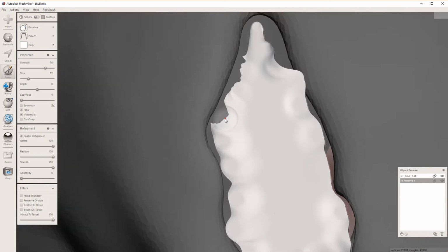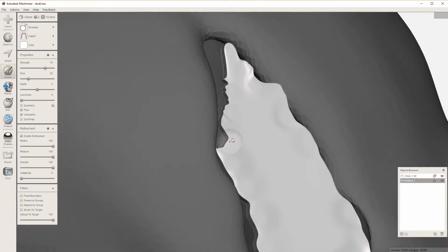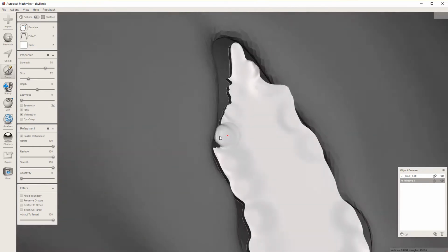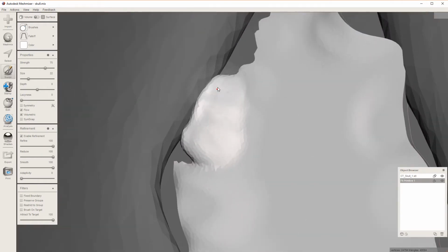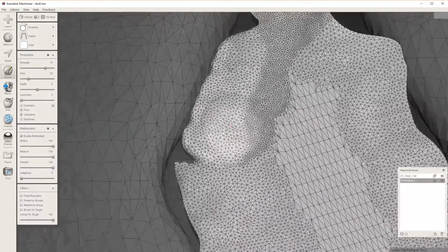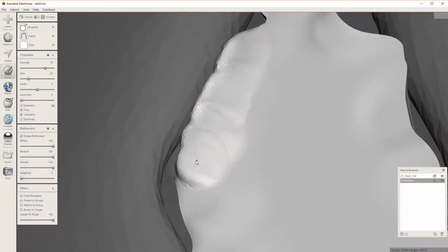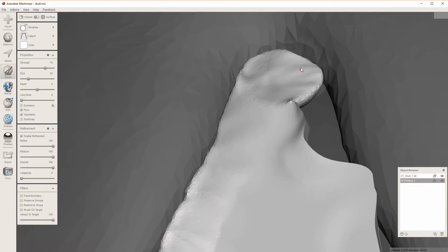Now what happens is, I'm recentering my view with the C key, by the way. Let's go right here. Now, when I click on this, it's going to get sucked to the closest target, the closest surface of the target. So as I go on this, you can see it's getting sucked in. And if I keep my mouse down, you can see all of these. That's the refinement going on, the refining and reducing. It's not actually creating more, it's just sucking to the edge. I'll turn off wireframe. And this is the really fun part. You just go around and it is being sucked to the closest part of your existing mesh.